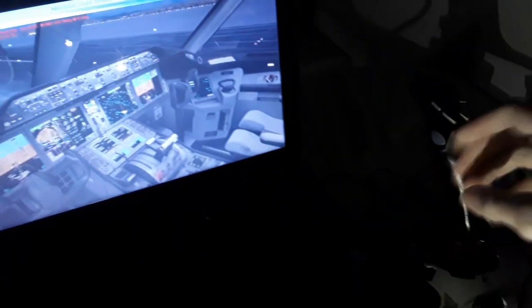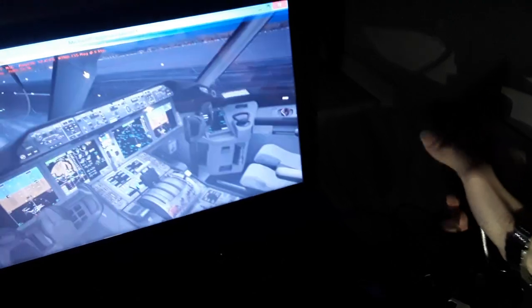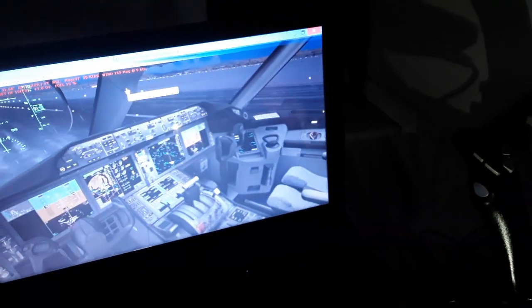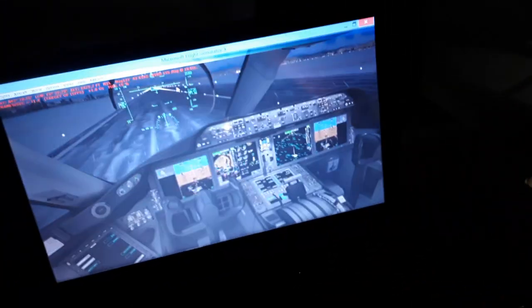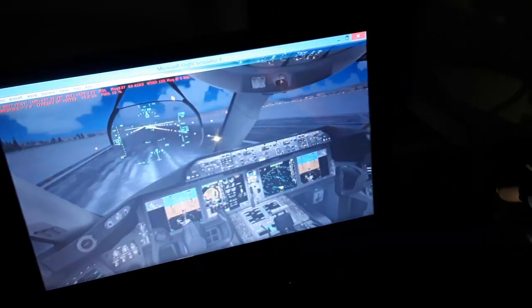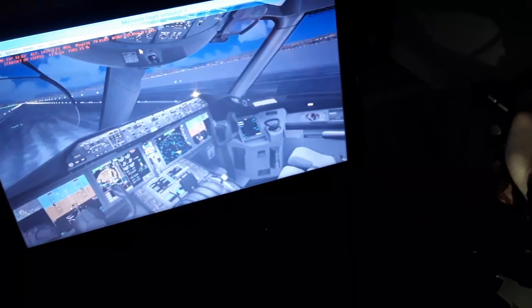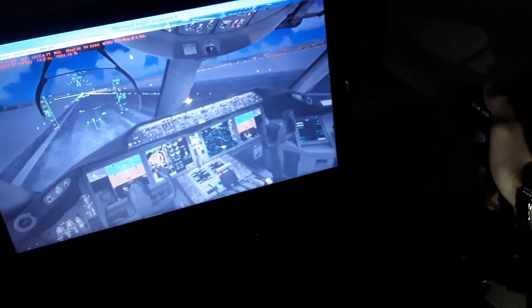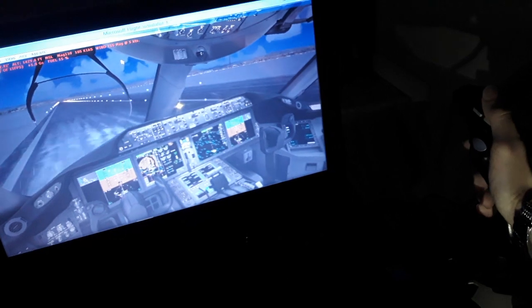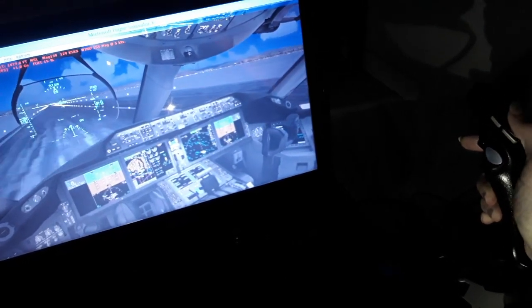You see now the full flight, manual flight. So we advance the thrust levers to take off. We need to stabilize first, then take off, go around. So we push the side stick or yoke down until 80 knots. We have 90, 100, 130. We want to rotate.